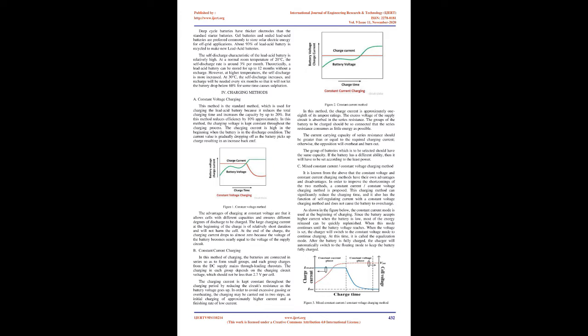C. Hydropower. Hydropower installations up to 10 MW are considered as small hydropower and counted as renewable energy sources. These involve converting the potential energy of water stored in dams into usable electrical power through water turbines. Run-of-the-river hydroelectricity aims to utilize the kinetic energy of water without the need to build reservoirs or dams.